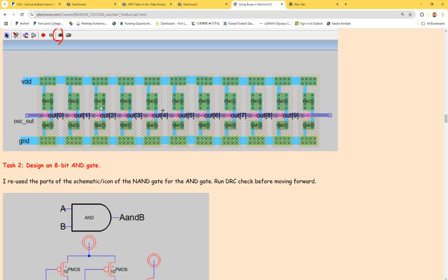But eventually, it's very difficult to create super fast oscillations using a crystal. It requires special materials, and that is why on chip, usually in integrated circuits, for very high speed circuits, we use ring oscillators to provide a clock. For example, a high speed camera, right? It may have 100,000 frames per second. A lot of times they use ring oscillators to create the shutter's signal. So it has a lot of applications because you can run it really fast.